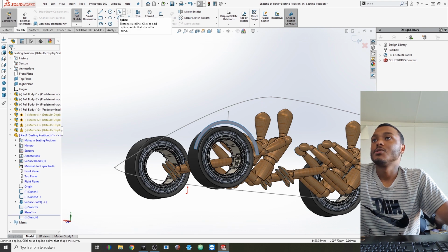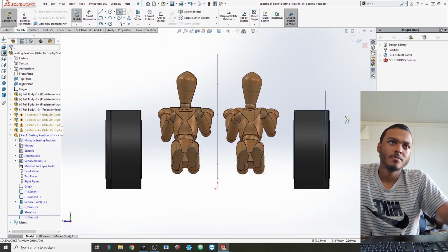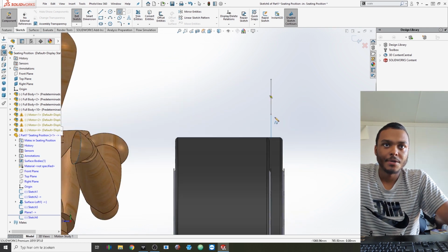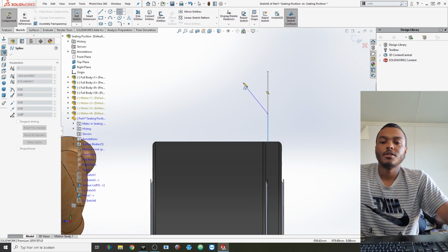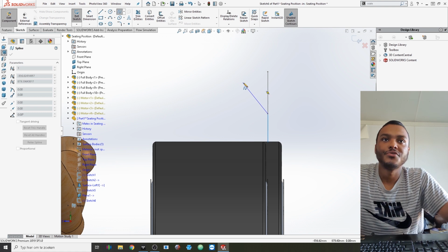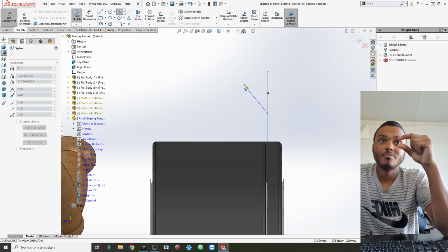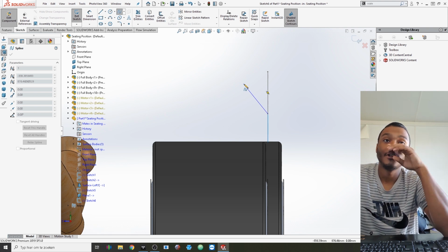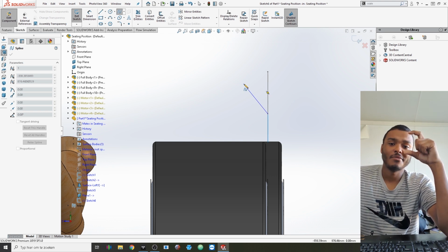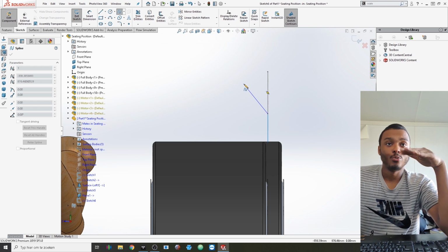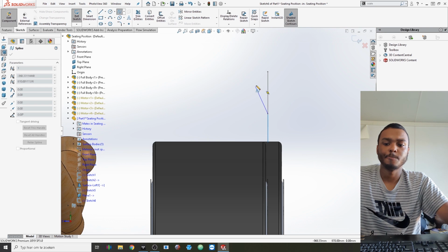So I also use a spline tool for this right here, and then also use the front angle, and then from this point right here, from the bottom of the sketch, I'm gonna draw the lines over that will be around the fender. And because we already have a 30 millimeter spacer between the wheel itself and that fender section, and then the start of the fender section itself is 40 millimeters, we already have something like 7 centimeters for wheel travel suspension.